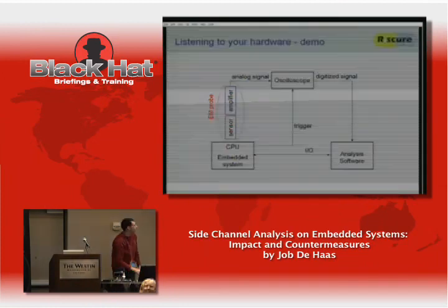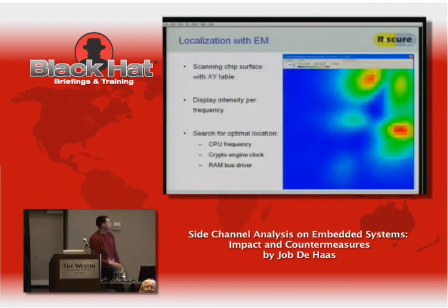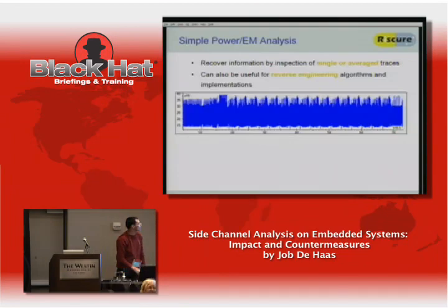Okay, so that was actually this explanation. So just move over. But like I said, you can do more. What we saw was looking at it like this. So again, you see a measurement of a DES. And that means that actually what you're already doing is reverse engineering, because you're looking inside the device and you may not even have an idea of what crypto it's using, but now you know it's DES. So you can use this to do reverse engineering of the device.